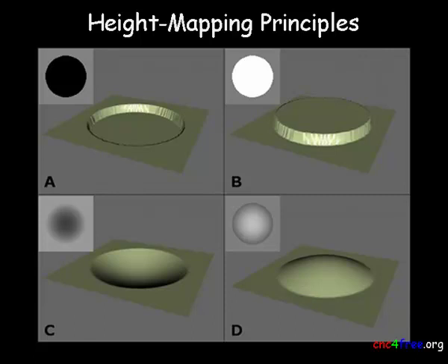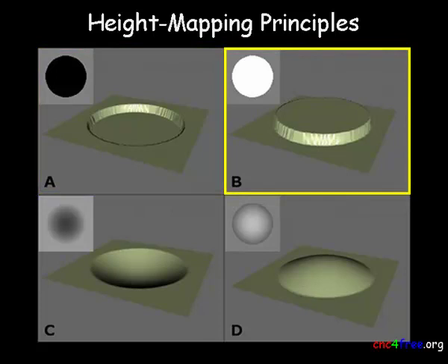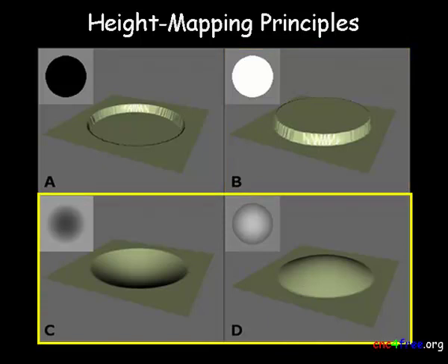Views A and B show the result of instant transitions in color value. Change from light value to dark, view A creates a downward step displacement. Changes from dark to lighter value, view B creates step-up deformation. Views C and D show how color gradient creates slope or curvature. Color distribution controls slope or curve of the mesh.